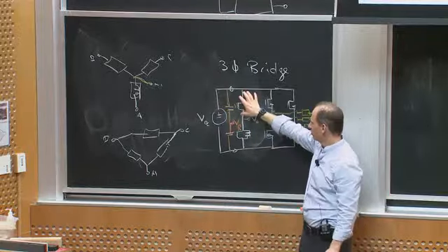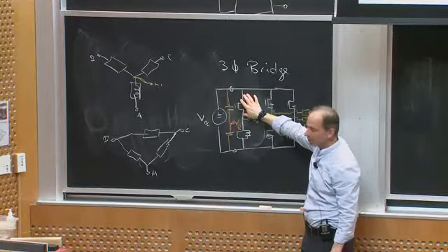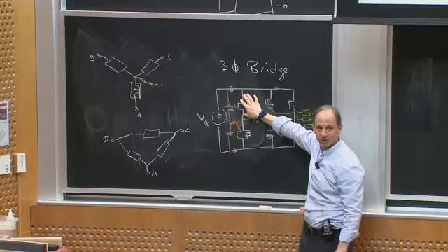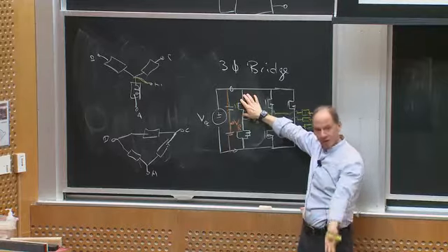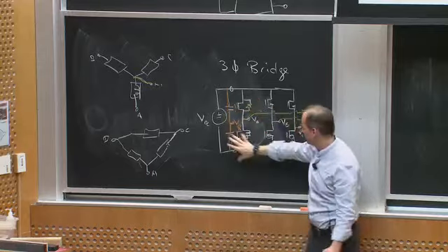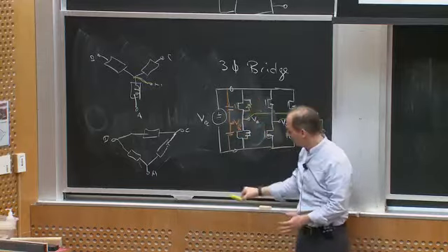So these are single directional blocking, bidirectional carrying switches. So this is a kind of voltage source inverter. There are also 3-phase current source inverters, just as there are with single phase. But again, this is vastly the most common.